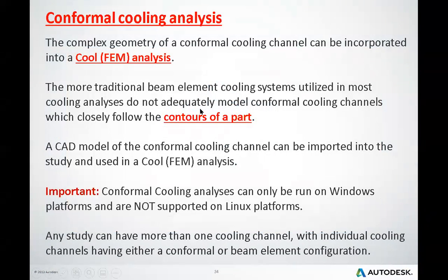And now the complex geometry in detail of the conformal cooling. The complex geometry of the conformal cooling channel can be incorporated into a Cool FEM analysis. We emphasize this because if we use the Cool FEM analysis, we can do a lot of shapes, whereas the more traditional beam element cooling system utilized in Midplane cooling analysis does not adequately model conformal cooling channels, which closely follow the contour of a part. This is a keyword as well.